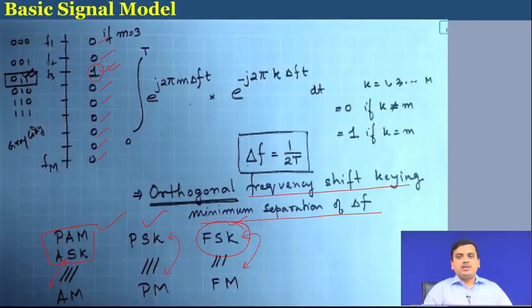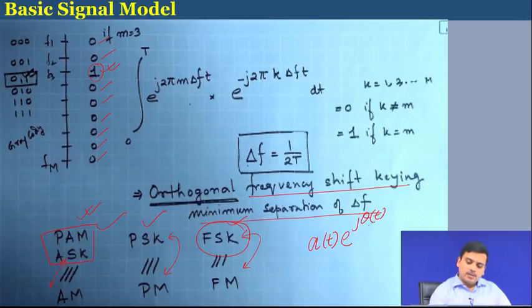each of the frequencies can be used to carry some data either via pulse amplitude modulation or via quadrature amplitude modulation. Now, why do we say this? Because as we know, if we have e to the power of j theta m t, theta m can be chosen by virtue of phase or by virtue of frequency, and if we do both, then we will not be able to distinguish the information bearing signal.